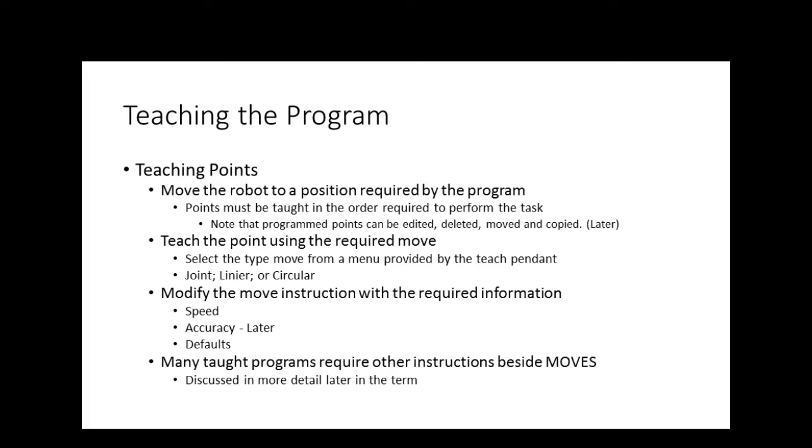Okay, so what we're going to do is jog the robot, and we're going to jog it using either joint, or we're going to jog it using either world or tool, which we very seldom use in this class right now. So these are the two predominant ones right here. When do you use joint? Well, we're going to use joint if we want to move one axis. What advantage does jogging the robot in world mean? Because all we're doing now is specifying a direction, right? So we're not concerned with what joint to move. All we're trying to say is I want to move it up, I want to move it down, I want to move it toward me, I want to move it in and out, which makes it real, real easy.